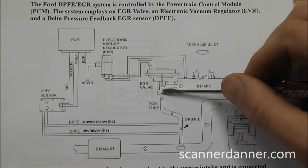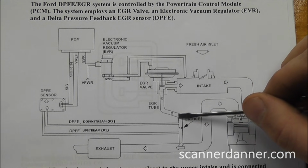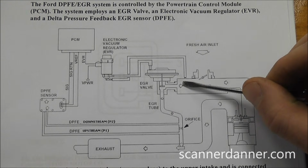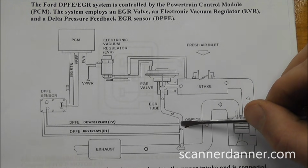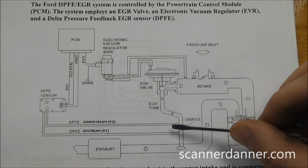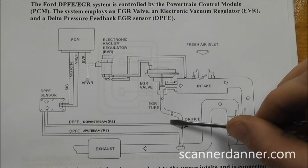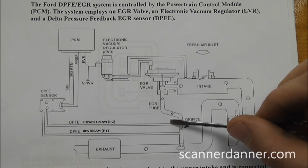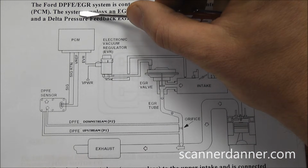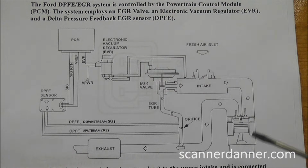Now, as soon as the valve starts to open, because of this orifice here, this upper chamber area will be exposed to intake vacuum. So the upper chamber area pressure is going to drop because of that. And so now we start to create a large difference in pressure here compared to the lower one. The greater the difference in pressure from here to here, the greater your signal voltage will be going to the computer. And that's how the sensor works. That's how the system operates.